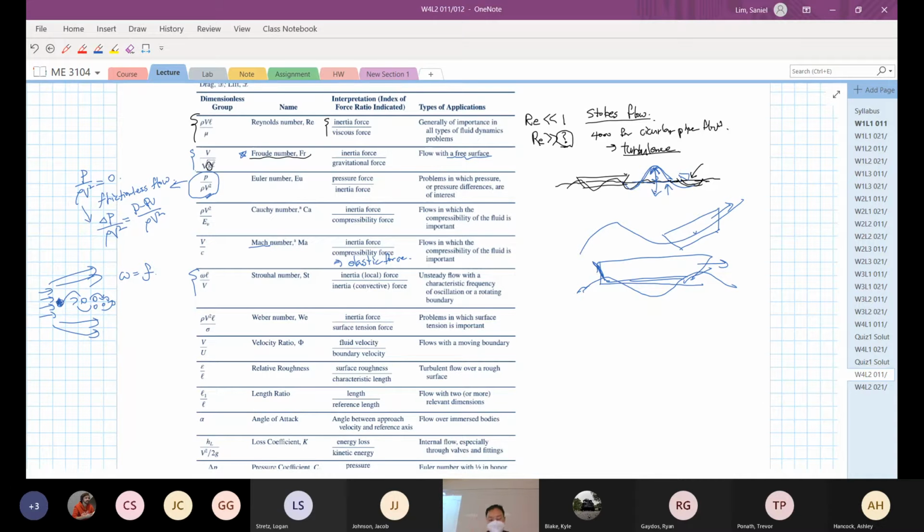The droplet forms the spreading area, and it depends on the inertial force, which is the velocity of the spray. So if you decrease the velocity of the spray, it narrows down to a small circular area. If you increase the inertial force, it's going to spread out more, right? Those behaviors of the flow can be explained by the Weber number.